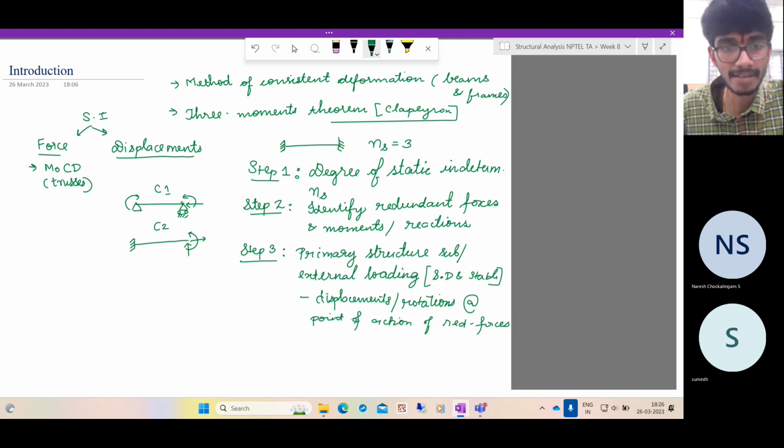The horizontal force acts so that this point does not move horizontally. Similarly, the vertical force is acting such that this point is held in place. Suppose there's a loading here. The horizontal force ensures that under the applied loading, this point does not move horizontally, and the vertical force stops it from moving vertically, and the moment restrains this small section of the beam from generating any slope.